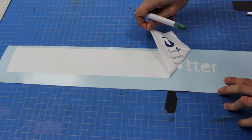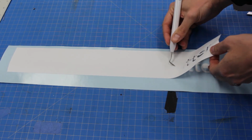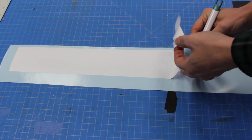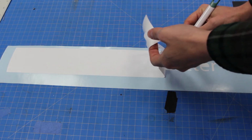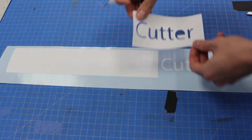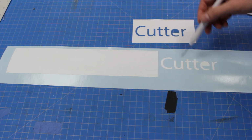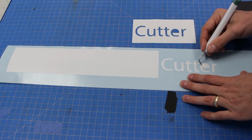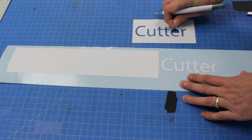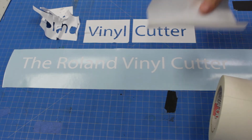When the vinyl cutter has finished, the job becomes to weed the background vinyl off from your artwork. If you put relief cuts into the artwork, like these vertical lines between words, it will make the weeding easier. There are special tools like these small hooks that can help you weed out the middles of letters like O's and E's.